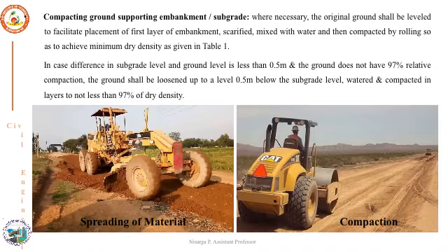Then the compacting of the existing ground must be done wherever it is necessary. The layer has to be first leveled and then compacted. You have to note that, if required, water has to be spread so as to achieve the OMC condition, and compaction will be done such that you achieve maximum dry density.